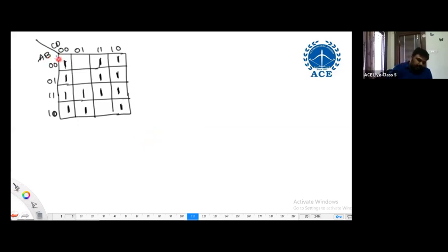Right. Let me do that. This is one grouping. Remember that we have an octave. Don't group these four separately, these four separately. You can group them, but those are not prime implicants. Yes. Second grouping. Right. Third grouping. Fourth grouping. And fifth grouping. Whether required or not doesn't matter here. Whether it is a prime implicant grouping or not, that's it. How many groupings are possible? 5 groupings which cannot be expanded. The number of prime implicants is 5.